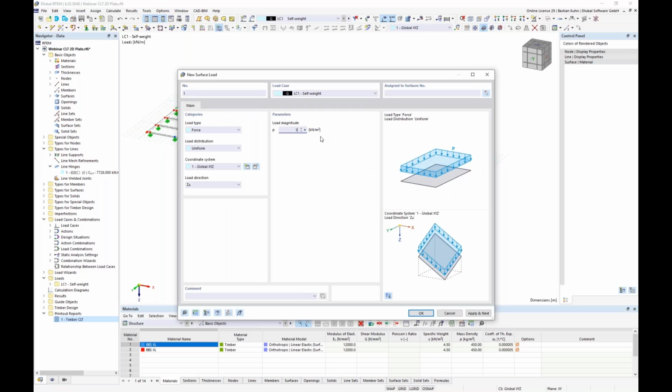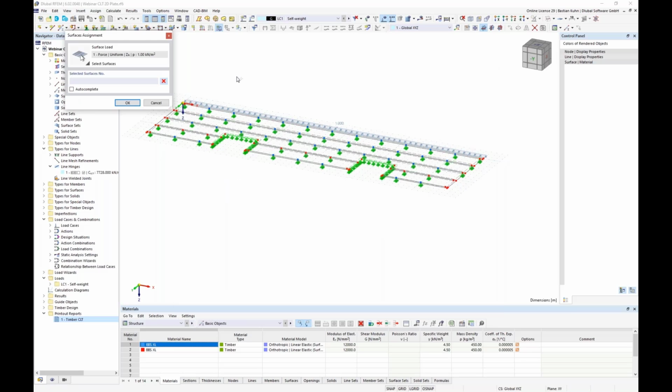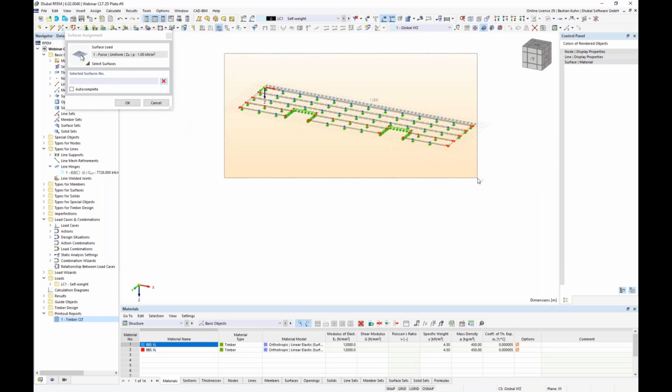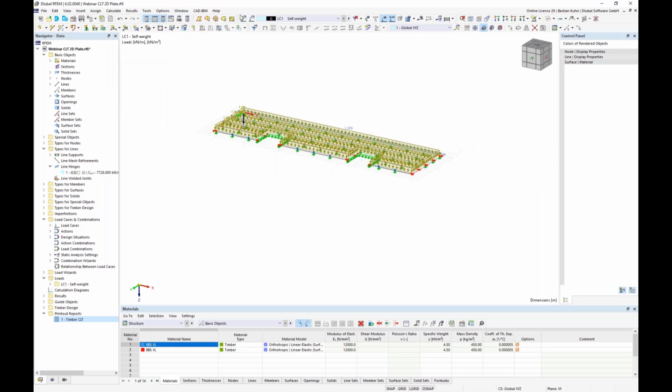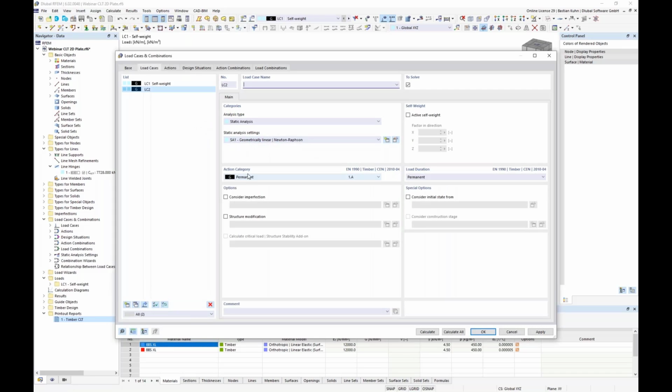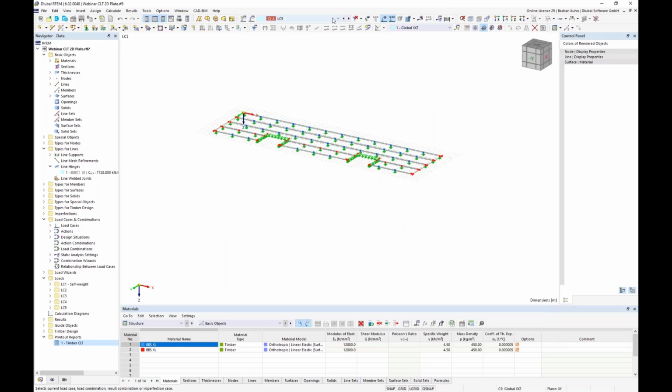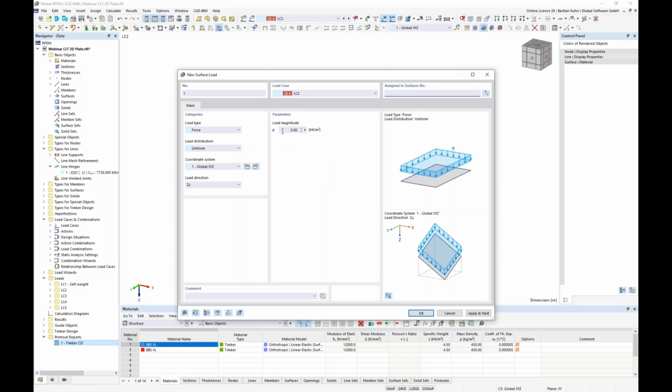We also take a small value in the load case 1 from self-weight and say, okay, we have that here. And now we define for each plate a live load. So this will be 5 times. Say, okay, and now also one of the advantages, if you compare it with RFEM5, and I worked long years with RFEM5, I'm still comparing it.